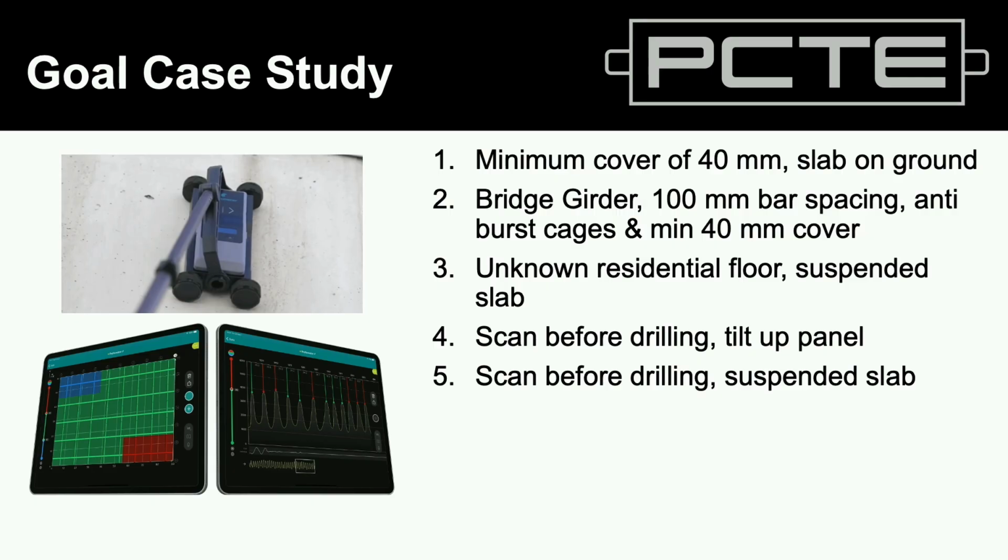So the hazard might be cutting reinforcing or particularly cutting post-tension tendons and reducing the capacity or integrity of the structure. Working on some infrastructure projects, they're very sharp about not touching any of the reinforcing. But also it's a safety issue for the drillers. If you've got power or plumbing or other hazards in that structure that could harm the person doing that work, they're not going to be detected with a cover meter. Yes, it might be interfered with by electrical cabling, but it won't let you know